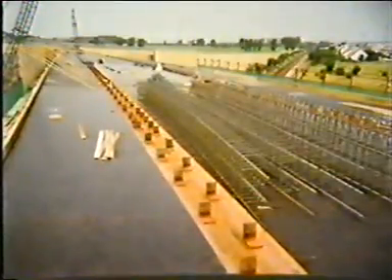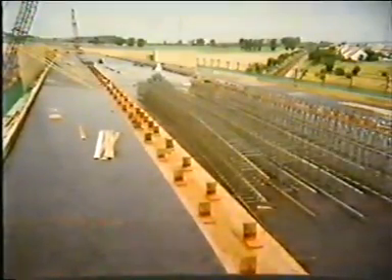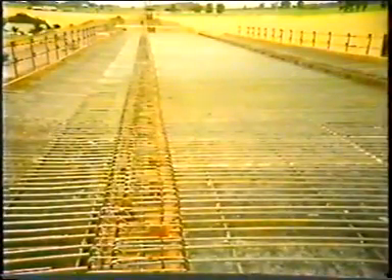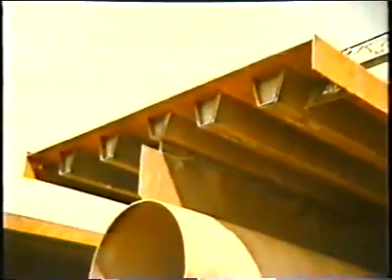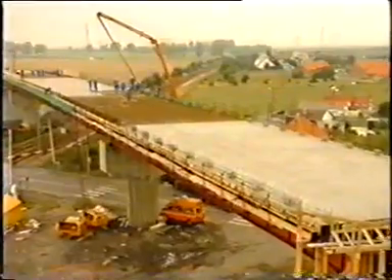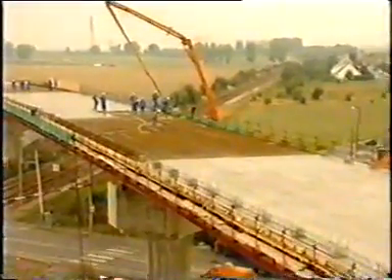The bracing for braking and traction forces is located at the same level, preferably situated as near to the rail as possible. The horizontal forces are transmitted to the cross girders and via the wind bracing to the supports. In a composite steel and concrete highway bridge, and bridges with an orthotropic deck, the deck serves as a bracing for all horizontal forces.